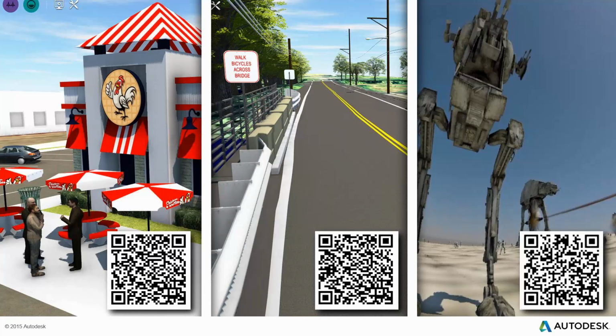One question was, can you embed a BIM model and export as a stereo panorama? I'm thinking a Revit building or something of that nature. I actually know this one from my own experience, because one of the stops on the virtual reality scavenger hunt at Autodesk University was a Revit building that I created. Same exact workflow. I dropped the building into Navisworks, placed my viewpoint in the building, published it as a stereo panorama, and it was the same result. So absolutely yes, you can do this with a building.